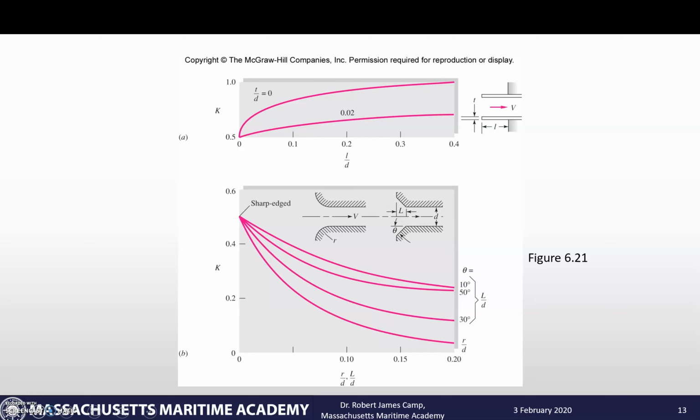We have the re-entrant entrance here, which is this one sticking out in the pipe. Here are ones for just a regular entrance. And see right here, sharp edge, 0.5. Probably the more common one that we'll end up using. But you can look at it.